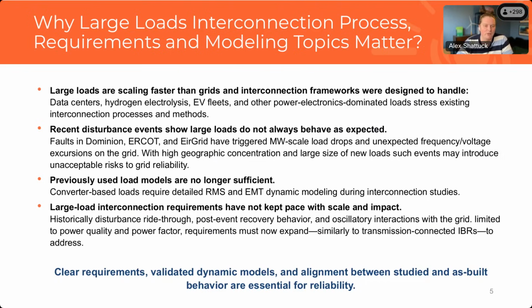The previously used load models aren't any longer sufficient. The converter-based loads need new detailed modeling during interconnection studies. The old methods of aggregating and modeling load may not be sufficient for these large loads, and specialized modeling is needed. And then lastly, similar to the others, the actual interconnections aren't keeping pace with the scale and impact of these large loads.